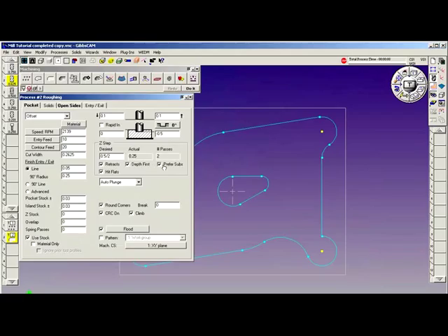Prefer subs is the option for forcing a subroutine for this operation only. And hit flats is a function of solids. Plays no role when machining geometry. In solids, it'll force a cut at each flat on the selected solid.